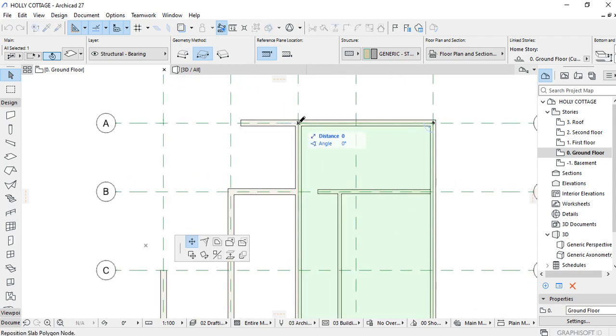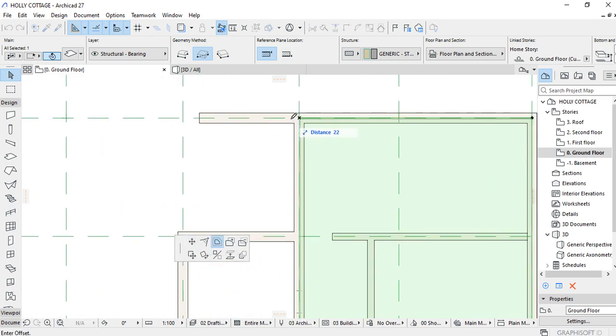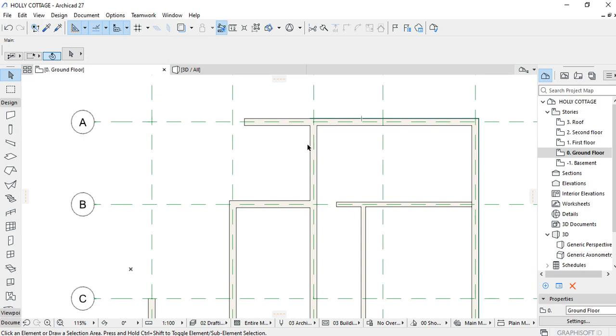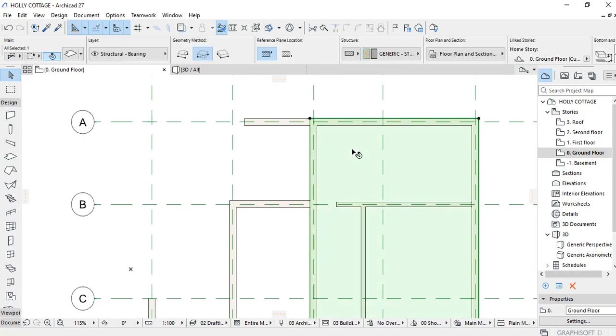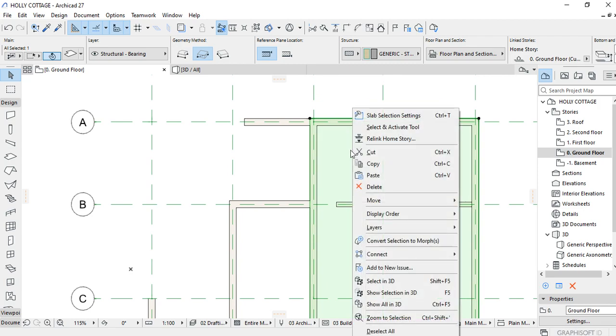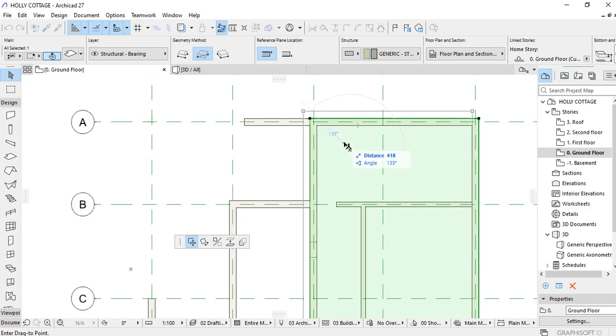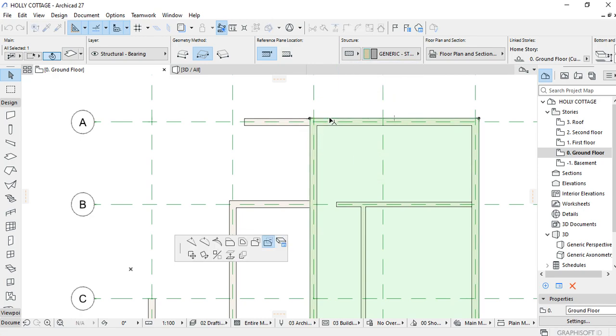So when you right click here, you could be able to choose offsetting all edges. So we can offset all its edges from here, say to there. Now being able to offset all the edges of this slab. So again, we could select it, then left click. You see, you could again drag it and move into another position. So you escape.